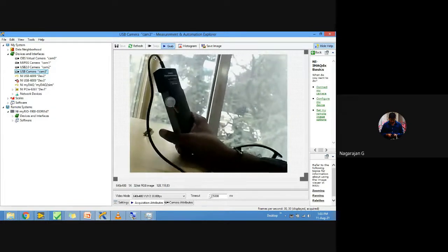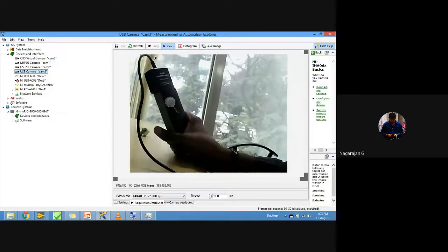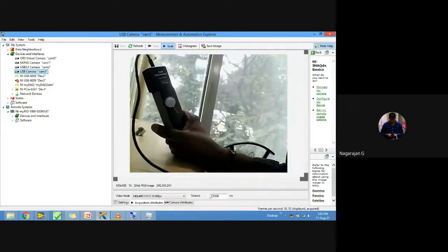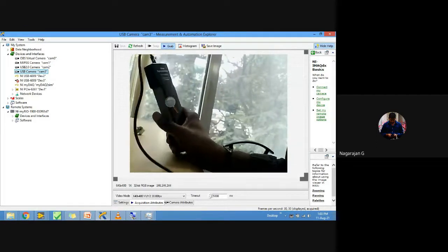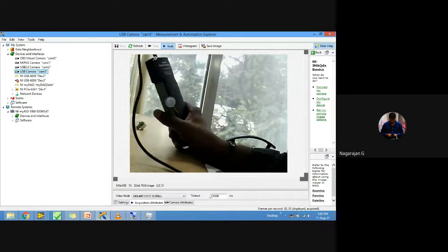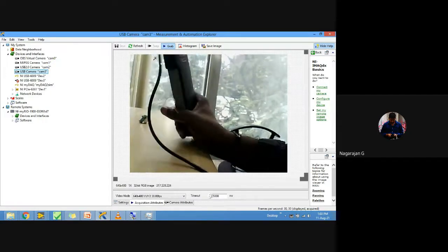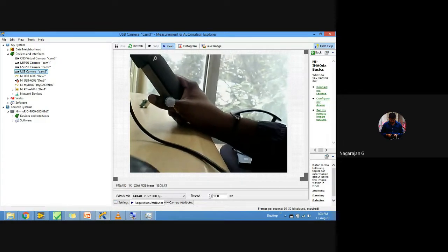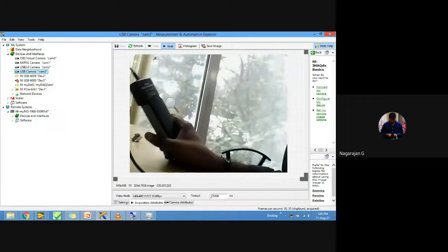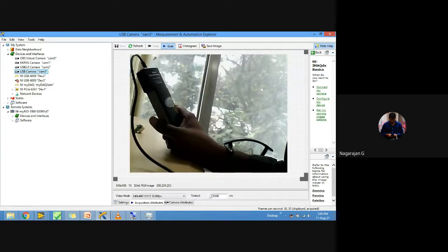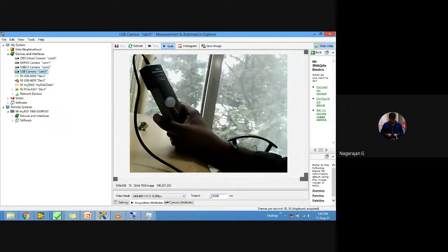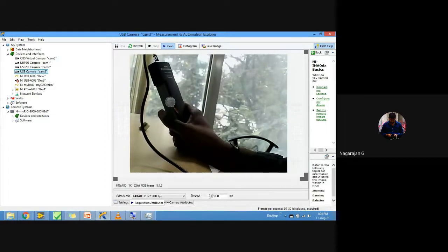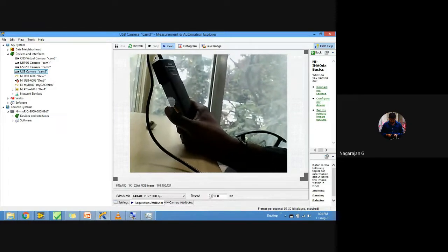Similarly, we have Vernier ECG and blood pressure sensors, which I cannot use by myself because the patient should not be in a mobile state when we try to measure the parameter. But I can use this one alone to acquire the information from the sensor. So I'm going to use this hand dynamometer to measure the grip strength and the pinch strength. The output will be in terms of voltage. In order to convert this into Newton, kilogram, or pounds, we have to do a small calculation, y equal to mx plus c, so that we can convert the voltage value into the respective physical parameters.